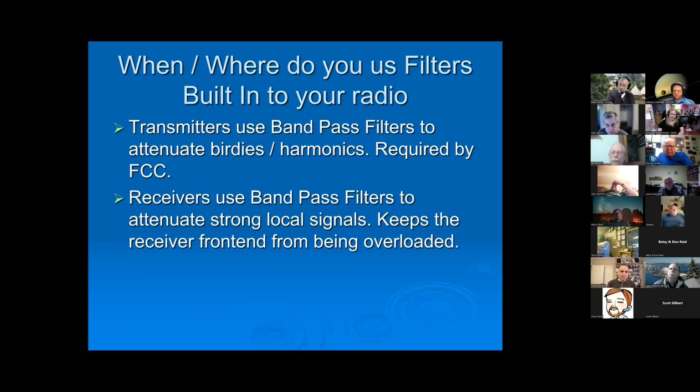Receivers in our radios also have bandpass filters. One of the things that we recognize is that if you have a really strong station that's up close to you, that RF may not be in the bandpass that you're listening to and trying to process, but it's strong enough that it can overload that receiver and cause it not to function correctly. So it overloads that front end and keeps that receiver from doing what it's supposed to do.